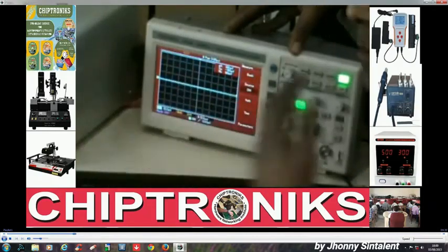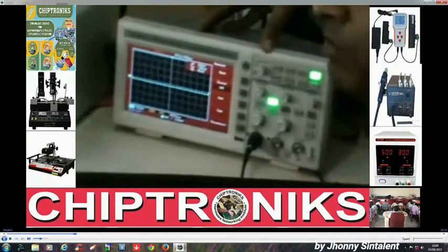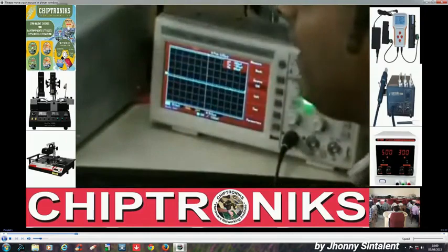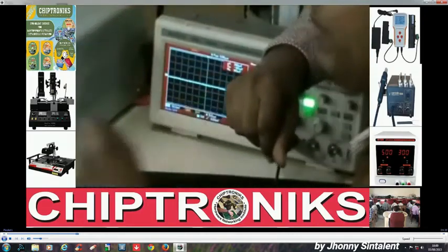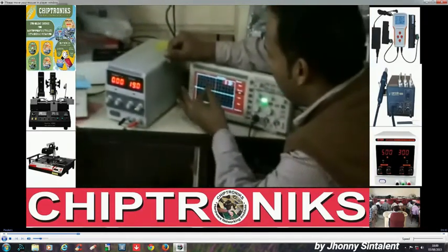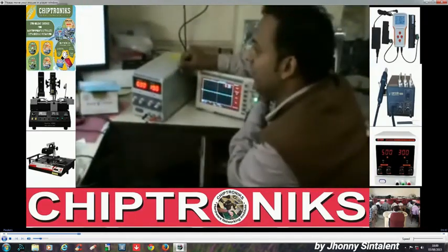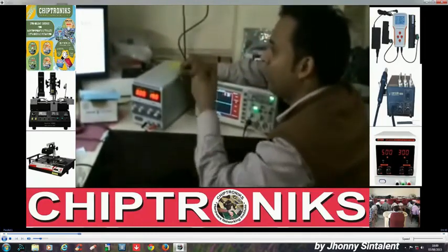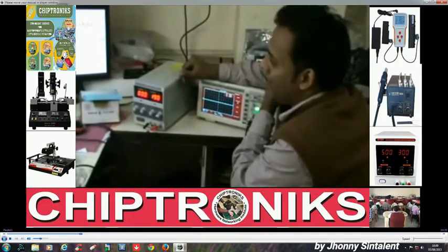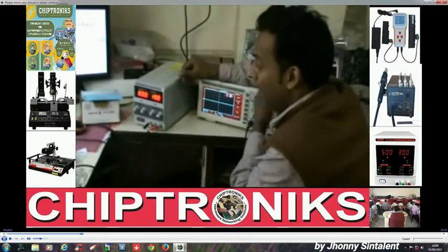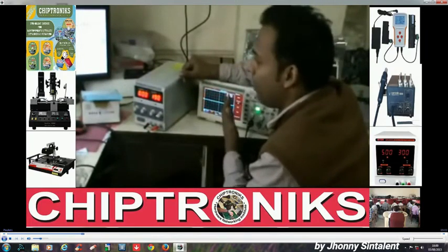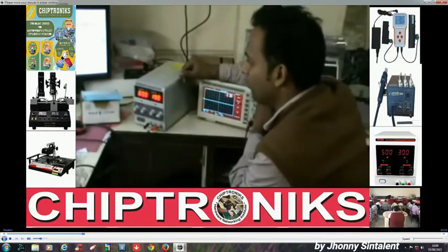The multimeter actually shows you average values, like 3.3 volt. But we must see the curve nature, whether the wave is coming or not, or if there is some fluctuation in it. So the oscilloscope is an important tool to diagnose complex problems, and we can trace the entire power sequence on it. After some classes, I'll have this class also.